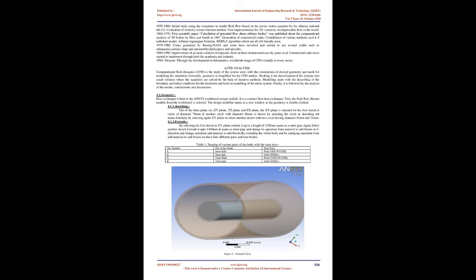Total et al. conducted an experiment in a double pipe heat exchanger by providing threads in the inner pipe. They observed that the Nusselt number and heat transfer coefficient increased for the threaded pipe, but the pumping power required also increased compared to the plain tube.